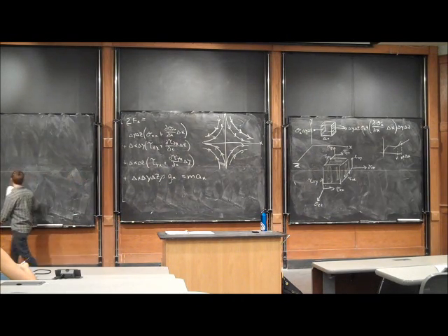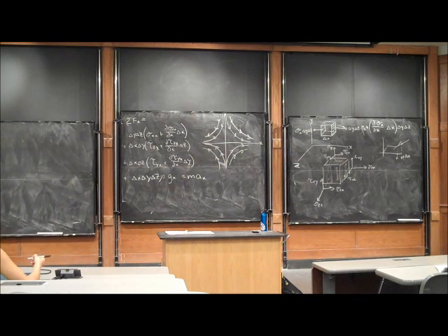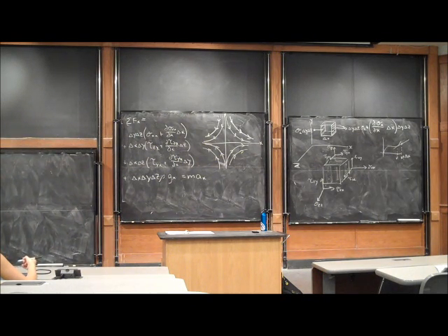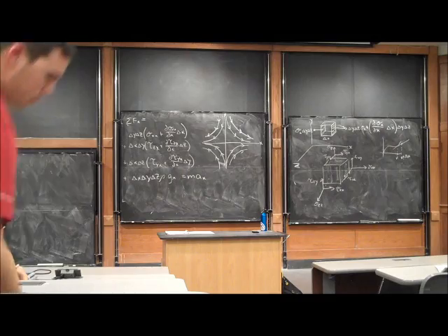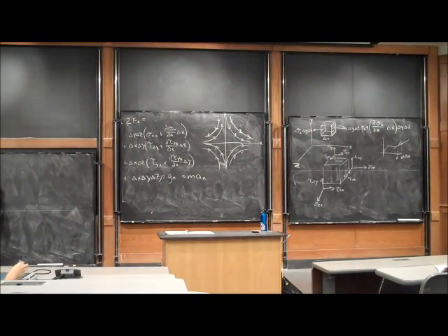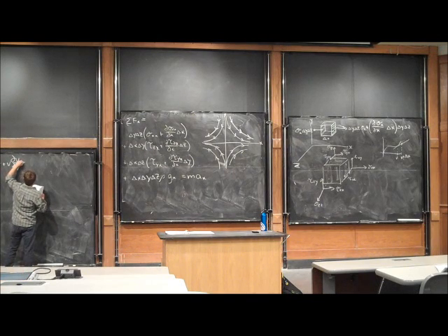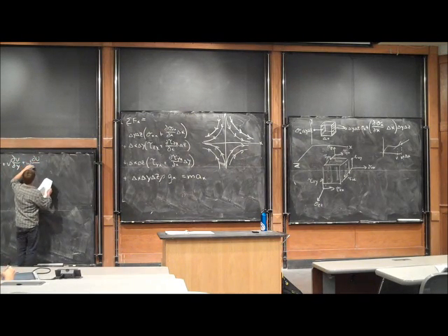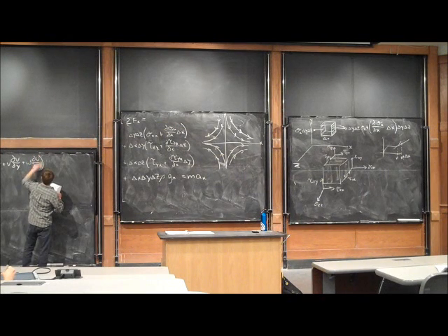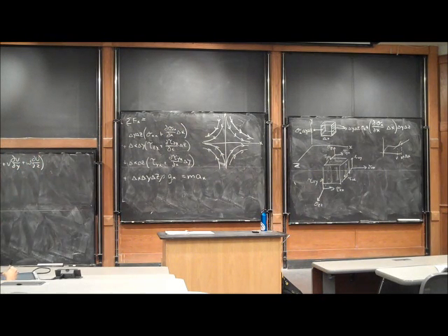So the sum of the forces in the x direction equals the mass, which is rho times the volume, delta V, times del u del t plus u del u del x plus v del u del y plus w del u del z. That was how we defined the acceleration in the x direction from the viewpoint we're taking.